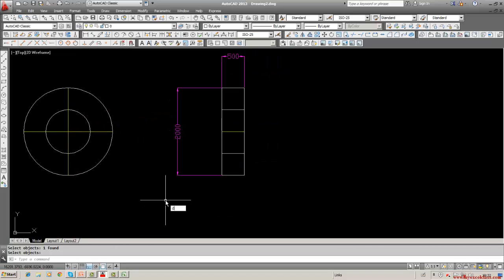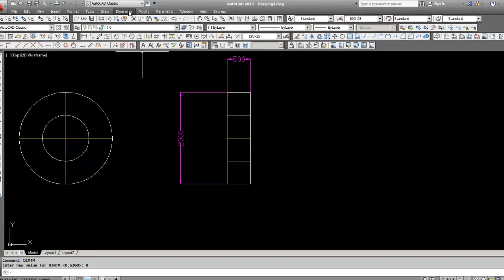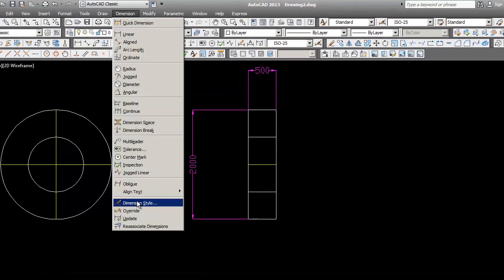So now, once again, dimension tolerance, switch on. This you have to do frequently if you are dimensioning. And then you go to the menu here, or here itself you can type DIM TP. TP is the upper level tolerance. You want it to be 0.063, you can type 0.063. And DIM TM is the lower dimension. It is 0. You can type 0. And you go there, I will show you how it has appeared.